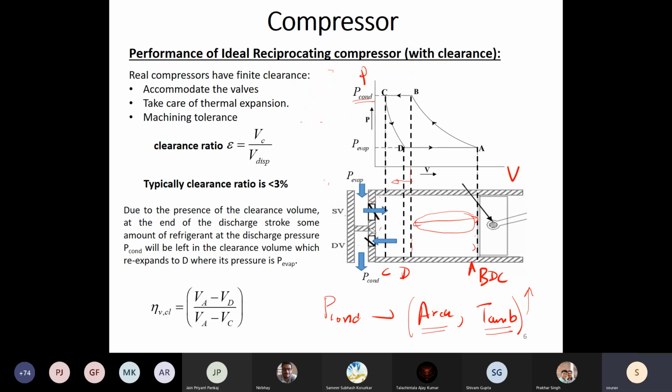It depends on the sizing, so that's why sizing is important. Let's say your evaporator is sized for providing 3.5 kilowatt, which is 1 ton of cooling. It means you will have boiling proportional to that amount of heat absorption inside the evaporator. So you have that much vapor generation, some m dot ref generated inside the evaporator, and that has to be sucked by the compressor.